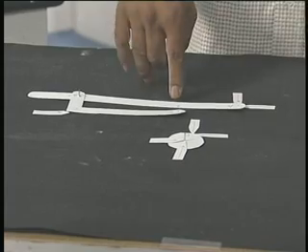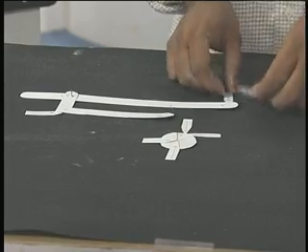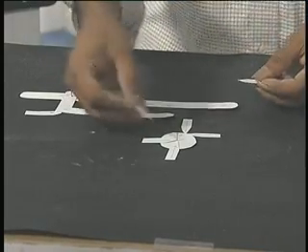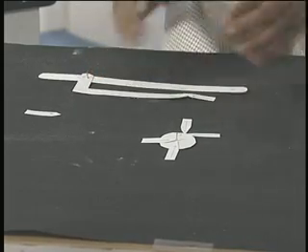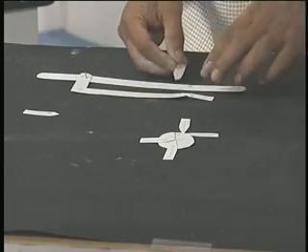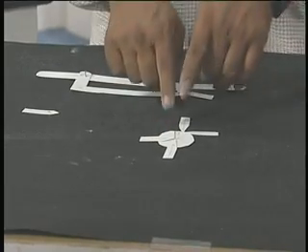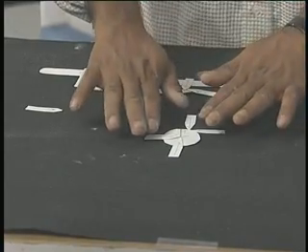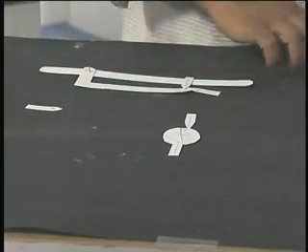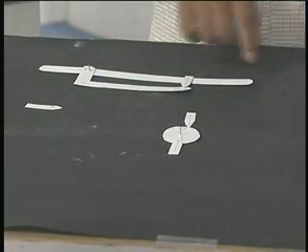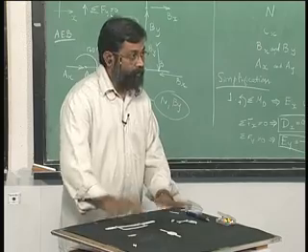Okay. An equal and opposite reaction has to be inserted over here. I am just going to remove this and insert it over here. There is a restraint this way, equal and opposite restraint has to be inserted over here. Let me just move it over here like this. There is one more like this that I have to insert. An equal and opposite reaction at D. Here we have made a simplification and to find out that these two are 0. So we might as well remove them, which means this is also 0. So you can do this kind of simplification in order to understand how to draw the free body diagram.